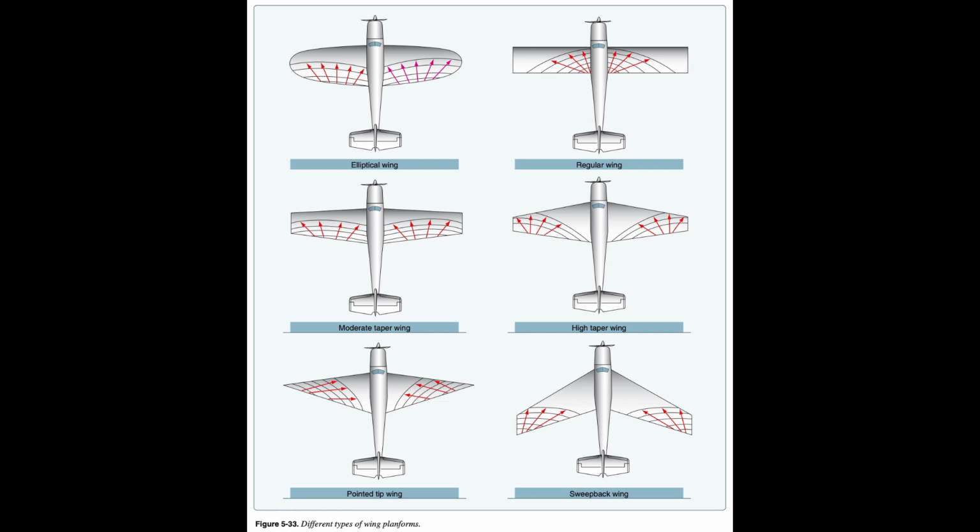The tapered airfoil is desirable from the standpoint of weight and stiffness, but again is not as efficient aerodynamically as the elliptical wing. In order to preserve the aerodynamic efficiency of the elliptical wing, rectangular and tapered wings are sometimes tailored through use of wing twist and variation in airfoil sections until they provide as nearly as possible the elliptical wing's lift distribution.